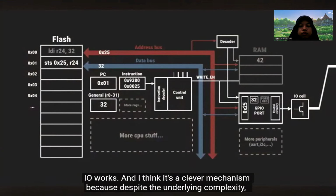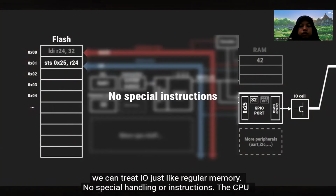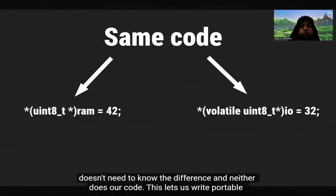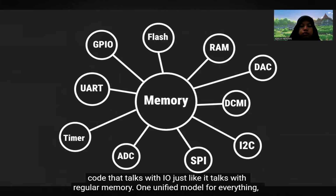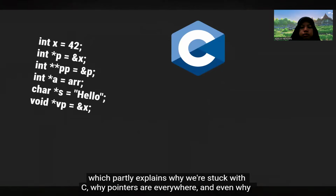And I think it's a clever mechanism because despite the underlying complexity, we can treat I/O just like regular memory. No special handling or instructions. The CPU doesn't need to know the difference, and neither does our code. This lets us write portable code that talks with I/O just like it talks with regular memory. One unified model for everything, which partly explains why we're stuck with C, why pointers are everywhere, and even why the volatile keyword exists.